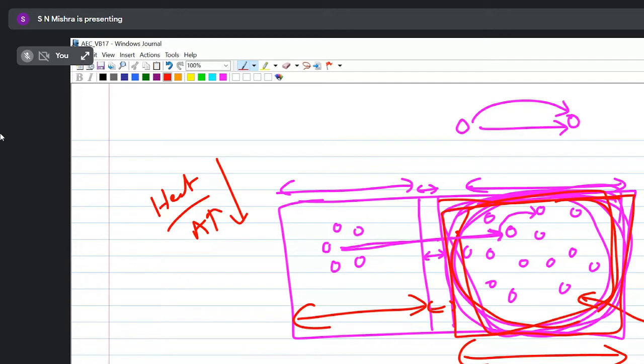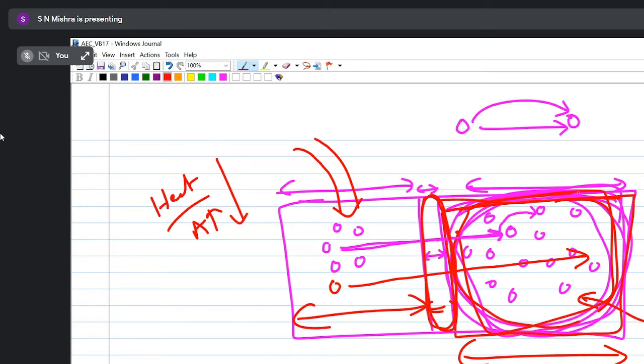So the main objective is to transfer the holes from emitter to collector. To maintain that, the emitter is heavily doped, and to minimize the recombination in the base region, it is thin as well as lightly doped, and to maintain lower heat or energy, the collector is lightly doped as well as wider in area. So this is the constructional view, and when the transistor is made, these things should be taken care of. Understood?